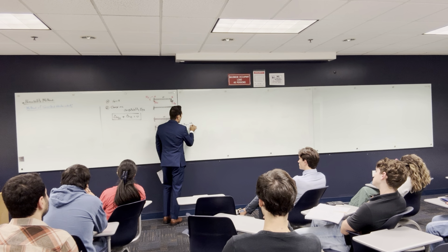the thing is, this concentrated load F, it's much better if I have something like that, and I put unit load 1 here, and I get the deflection of the unit load. And I'm going to call the deflection of the unit load here delta small 1, and I can replace delta 1 and say that delta 1 is equal to F delta 1. Is that right? So basically, rather than putting the full value of F, I'm going to take only 1 unit load and get the deformation this.